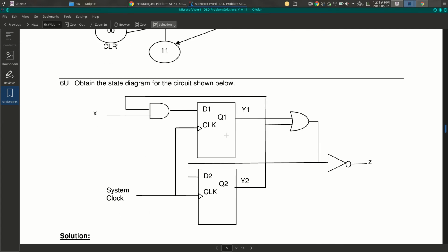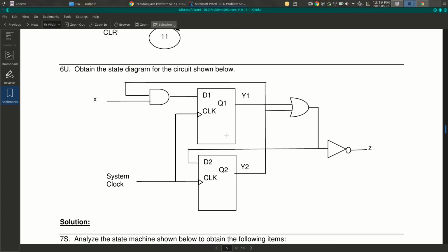So for example, this one's not too bad. Let's go to this one, which is really confusing, I think. Where the heck does D2 come from down here? Well, it can't be coming from the inverter because this is an input to the inverter, and D2 is an input. And if it was connected to this line, there'd be a dot right here, right? And if it was connected to this line, there'd be a dot. But if things are meeting in a T, we don't need a dot, because there's no option. It's got to be a connection.